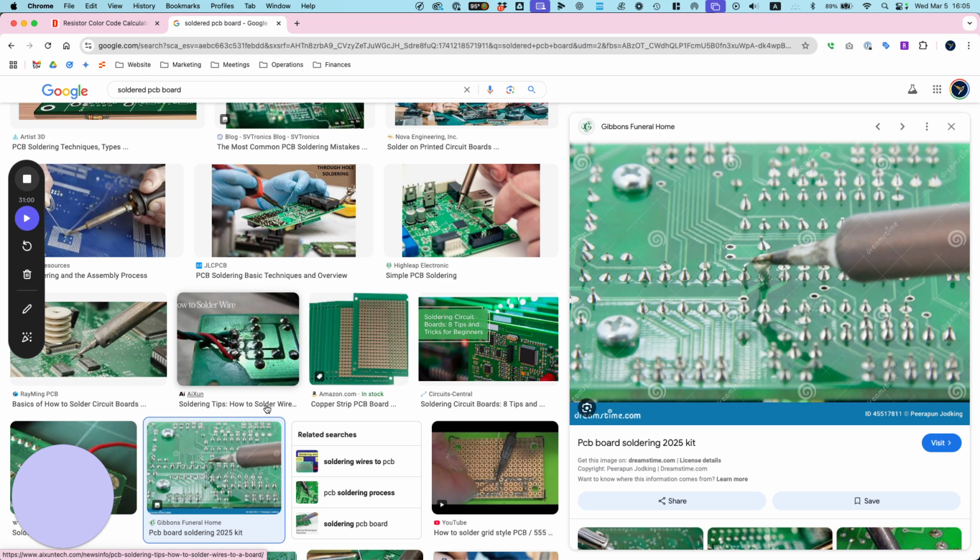these, just like your circuit board, are connected. So they're connected downwards. They don't list every number, but we have 0, and then 1, 2, 3, 4, 5, 6, 7, 8, 9, 10. So anything here, A5 through E5, are all connected. Let's just verify with the multimeter. I'm going to borrow yours. Okay, we can verify that they are indeed connected.